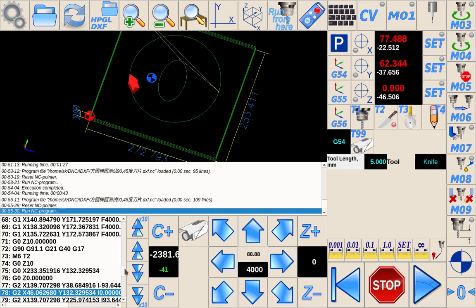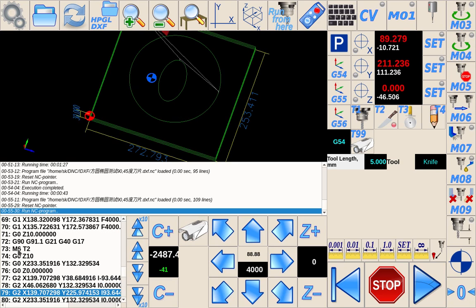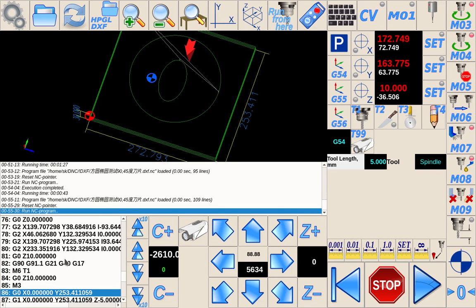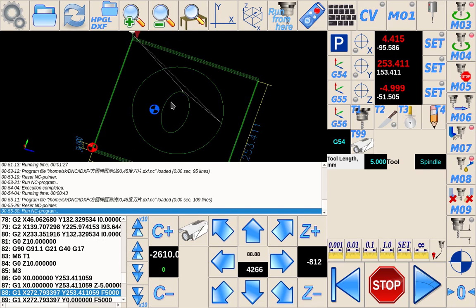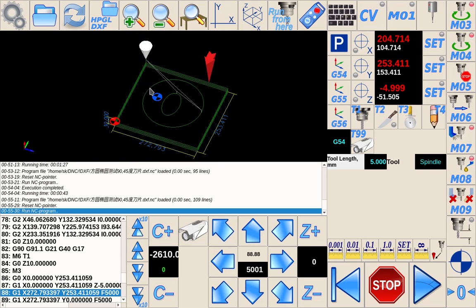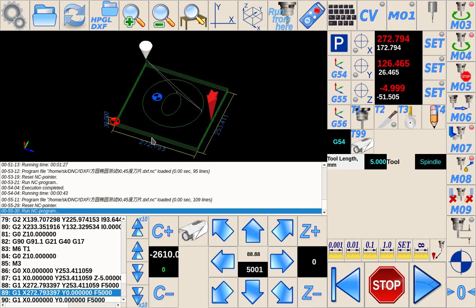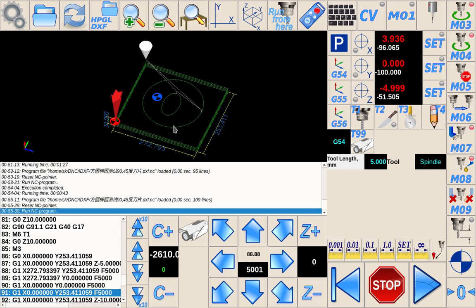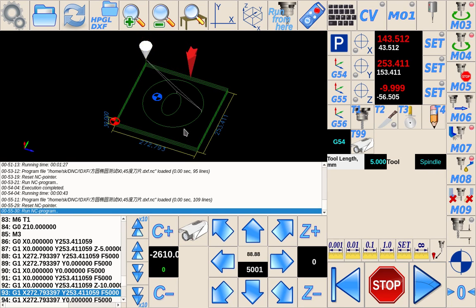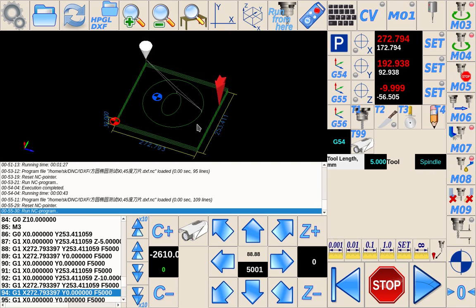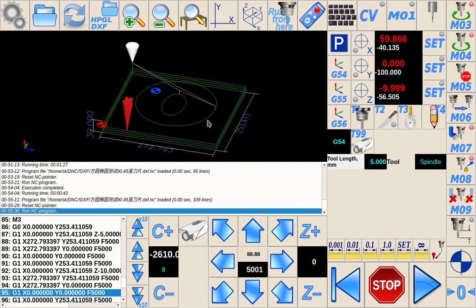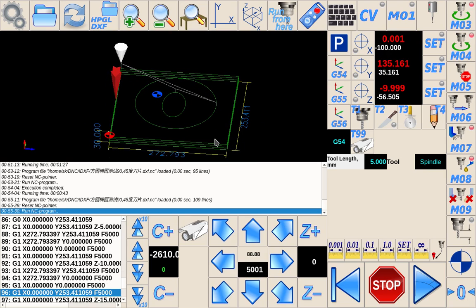And the code M62, M61 is automatically inserted into the code. So by writing correct macros for tool change, it's possible to handle switching heads, apply offsets between the cutting head, the knife, or creasing wheel or something like this. So everything is supported in software.